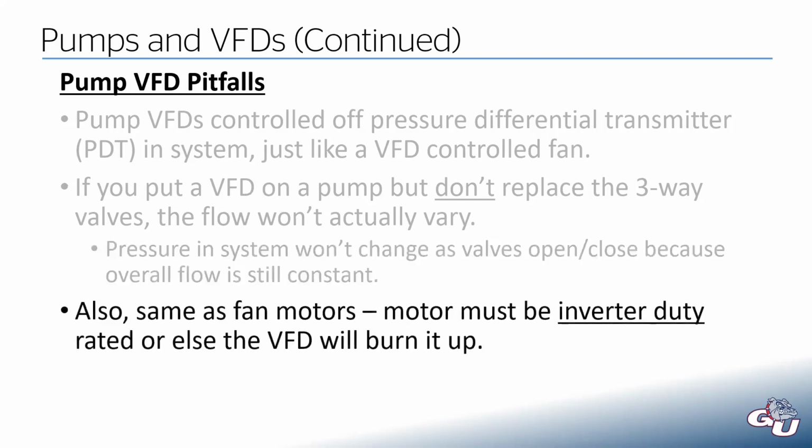Also, this is somewhat review, same as fan motors. If you're upgrading a pump, that motor has to be inverter duty rated or else the VFD's going to burn it up. The motor's not going to explode or anything like that, but within months or maybe a year, it'll be toast.